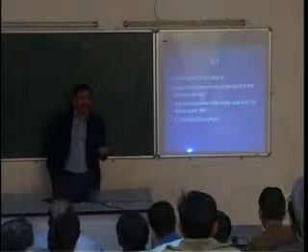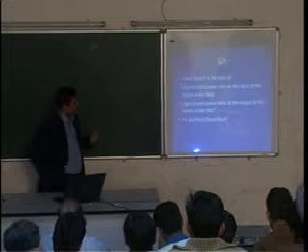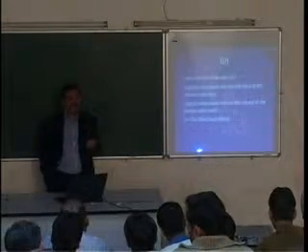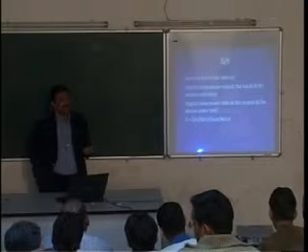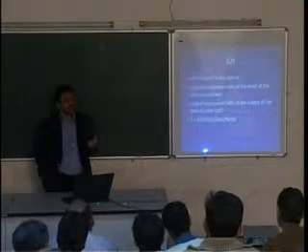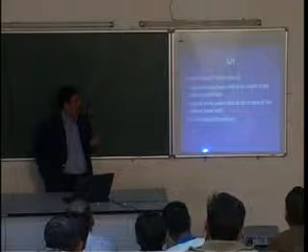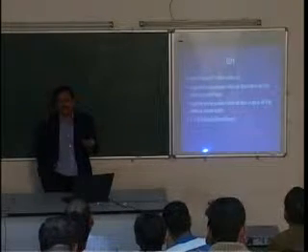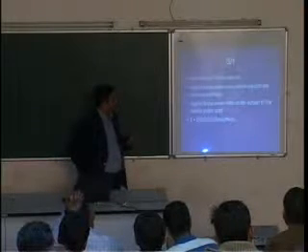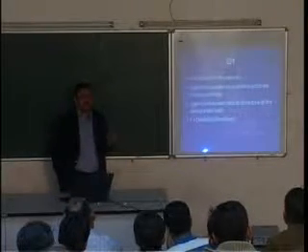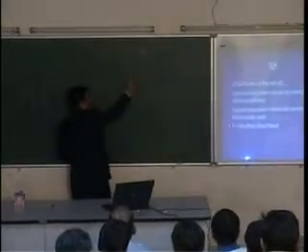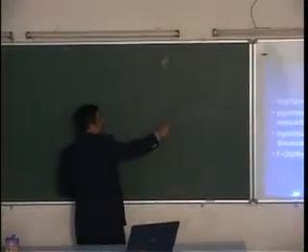You know the noise temperature due to, suppose, a dissipation loss, but you need to measure them. Even the noise temperature which the antenna is picking up, the antenna noise temperature itself, depends on your side lobe components and what type of source it is looking towards. If the antenna is looking towards the sky, then in the sky you have many galactic sources. These sources